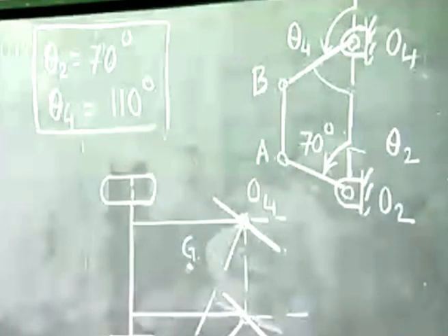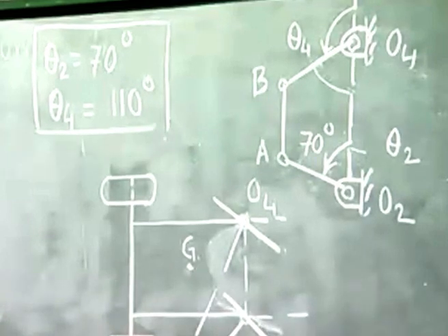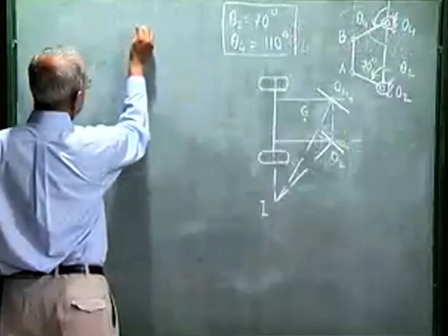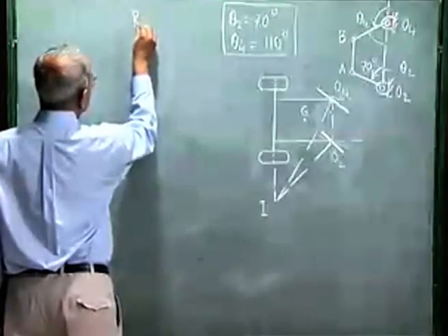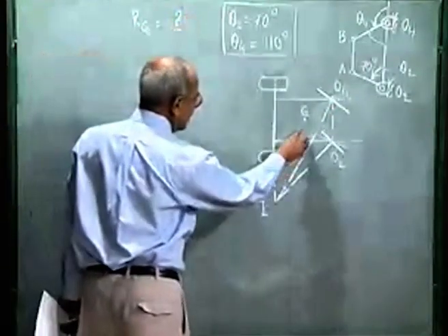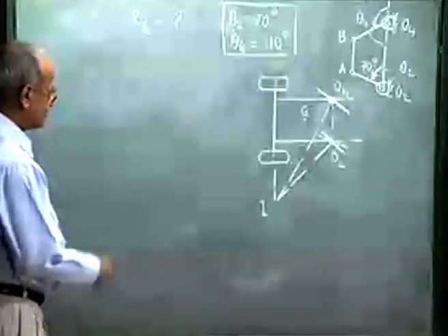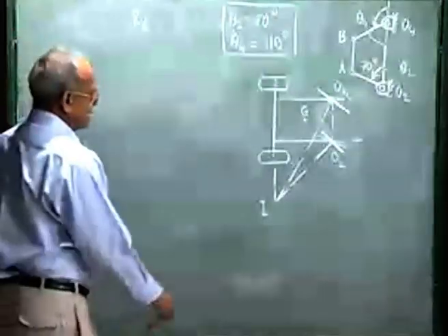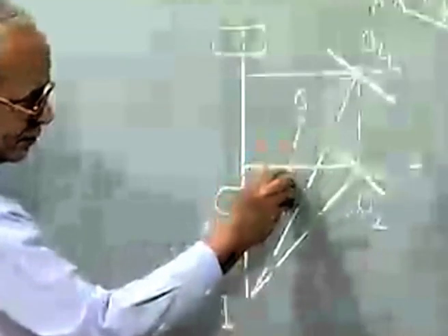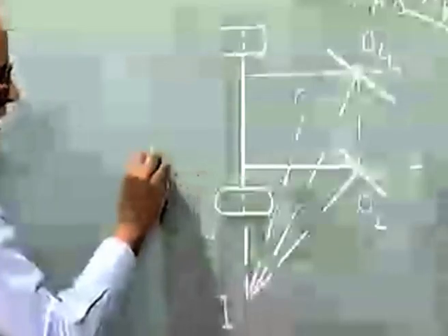Symmetric linkage takes care of the right hand and left hand turn identically. So we are left with only one more accuracy point. Let me take it as Rg, for which value of the radius of curvature of this center point G I must satisfy the requirement. And let us say the wheels have to rotate for that value of Rg. This I call Rg.